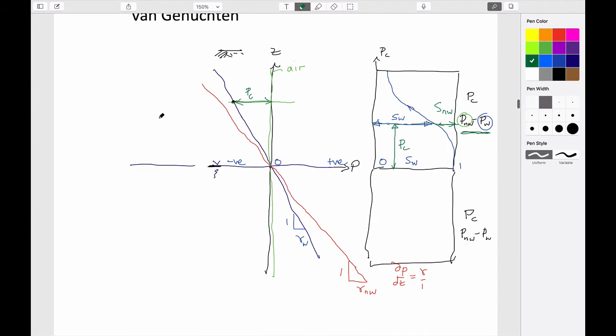All right. So now let's go below the water table. So below the water table we have two fluids. We have the non-wetting fluid, which is now denser than water instead of being much less dense, which is maybe 1.6 times the density of water. So if we take this and we draw this upside down, hopefully this is going to work out. And we do the same things. We take a particular height here. We have two fluids. We have a non-wetting fluid, which is the NAPL. We have the wetting fluid, which is still water.